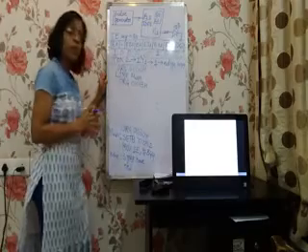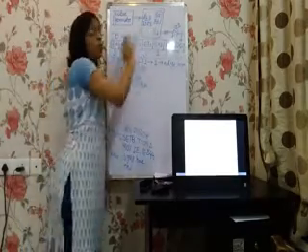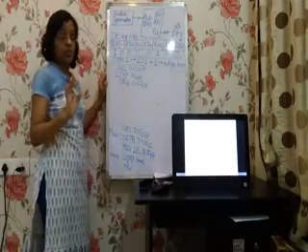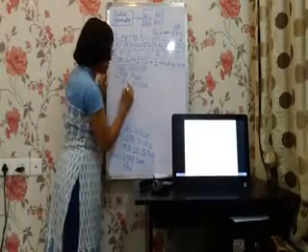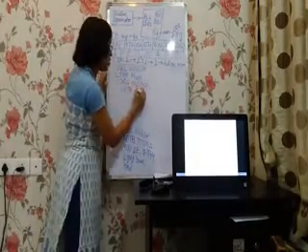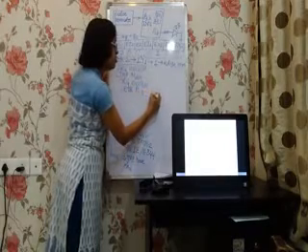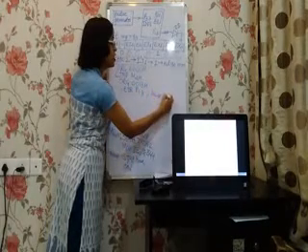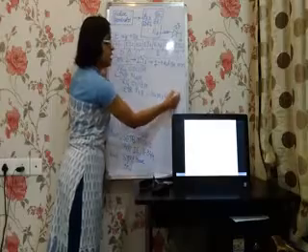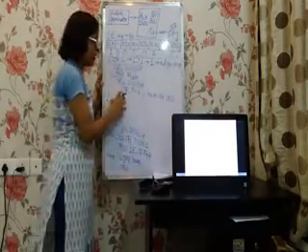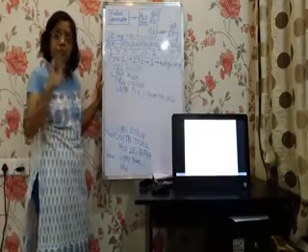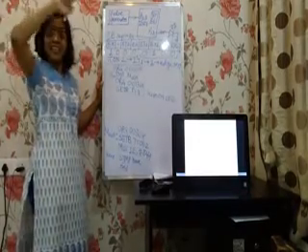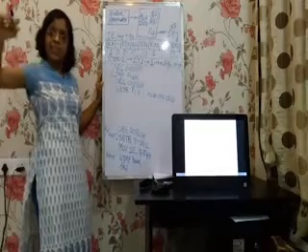And now what do I have to do? It is connected to an LED. The LED is turned on whenever a pulse is sent, so I will turn on the LED. SETB P1.3. What does this do? It turns on the LED. My LED will be turned on. Then we have to wait for some time, because it is high, delay, low, delay and so on.